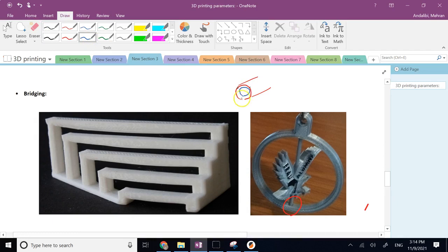Also, when you print the shaft, below the shaft, between the shaft and the hole here, there should be some support too. But again, if it does it very fast with bridging and leaves nothing behind, then what can you do? You can have a functional bearing, and you can print this whole part in one piece instead of two pieces, and then assemble them together, which is not really easy for plastic parts like this.